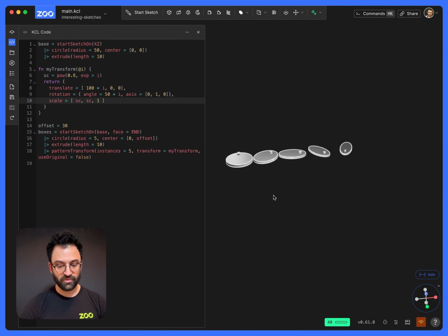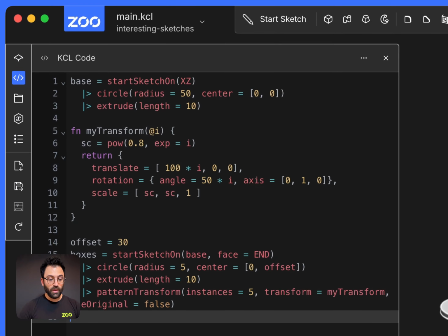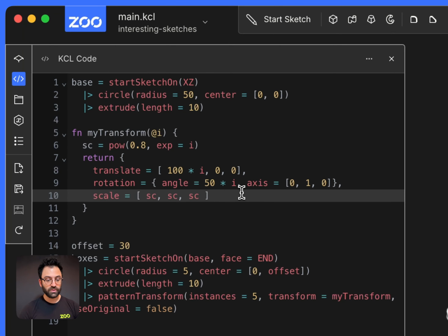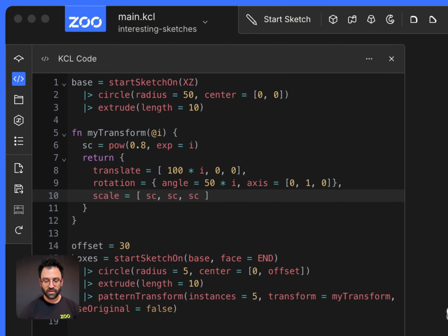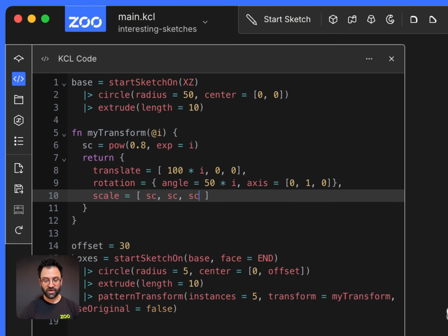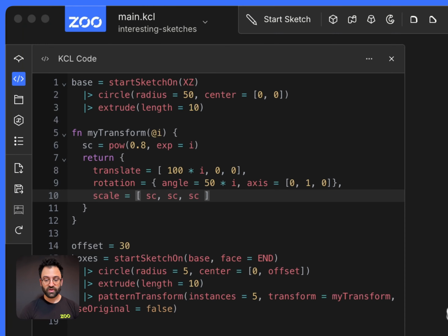There we go. So now the rotation is working nicely. Okay, cool. So let's move on. Let's make a more advanced pattern transform, because right now all we've really done is show an evolution on the linear transform. But you can use pattern transforms to do some really interesting things. For example, we can use them to make a 2D grid shape. So let's try that out.